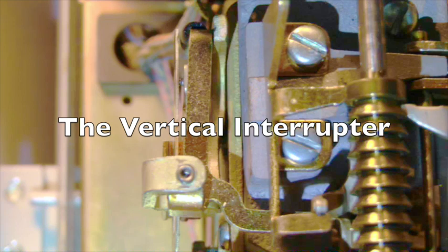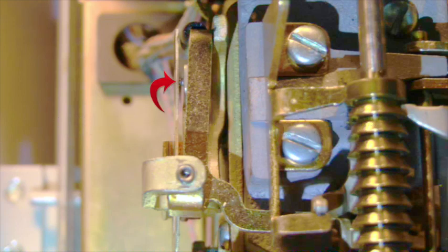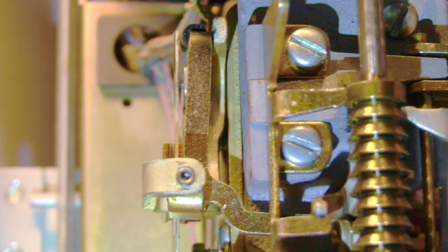Also associated with the vertical magnet is a set of contact springs called the Vertical Interrupter springs. This spring set is operated by a bell crank or L-shaped pivoting lever. Each time the vertical armature is attracted to the vertical magnet, the extension arm of the armature pushes upwards on the lever, causing it to pivot and operate or open up the contact springs.